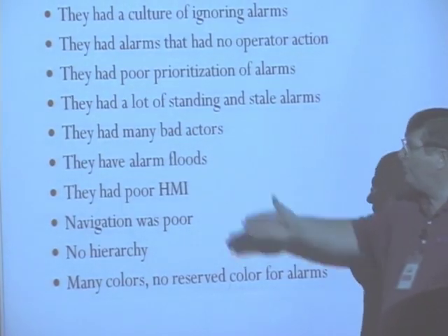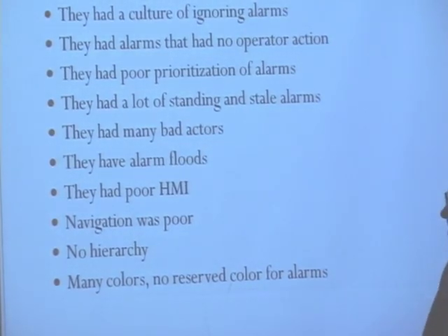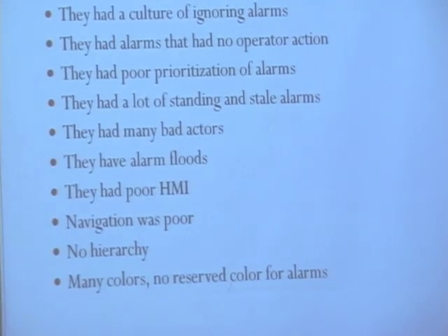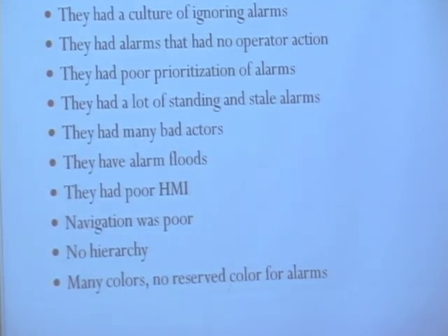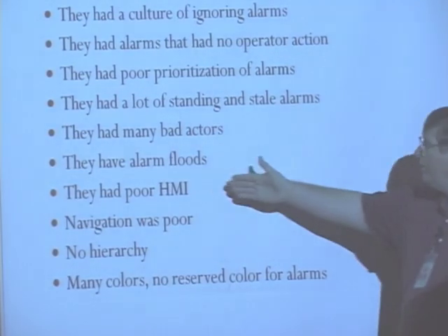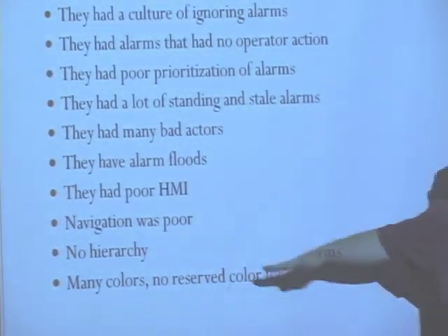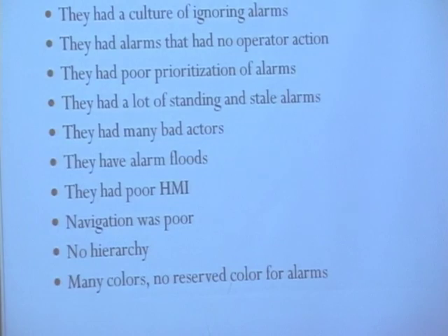They had alarm floods on a regular basis. And what we see is, if we have an alarm system that is badly designed, you will see more alarm floods. As you get your alarms under control, the floods start reducing. The two things go together. They had poor human-machine interface. Navigation of their graphics was poor. There was no hierarchy in the graphics.